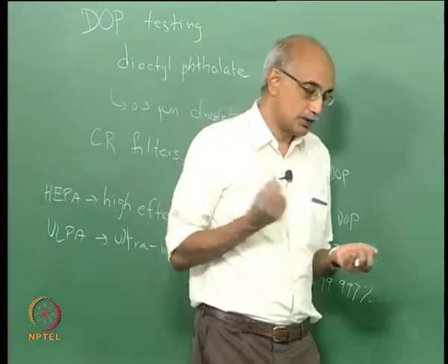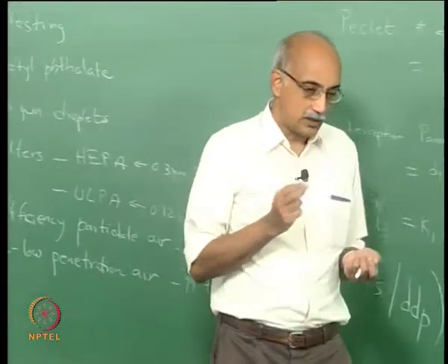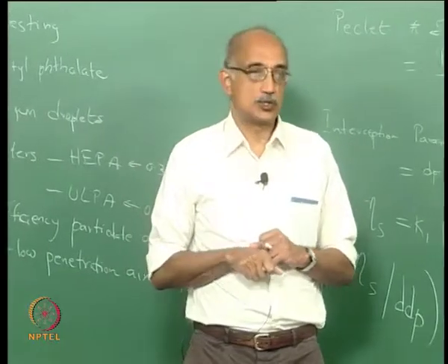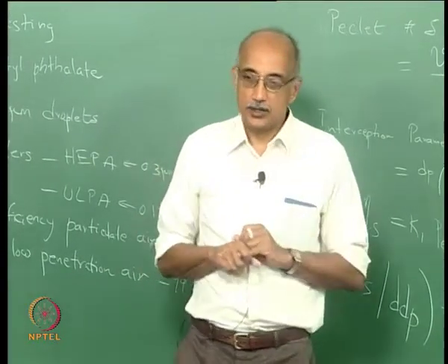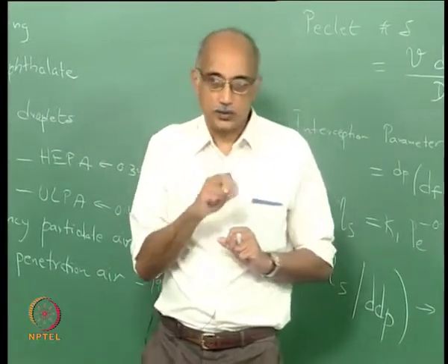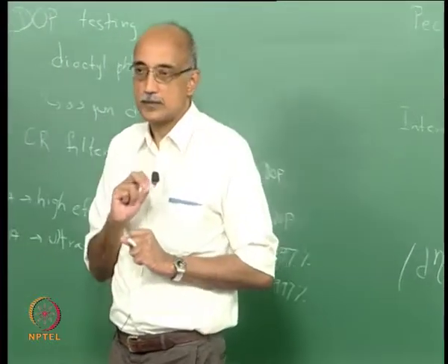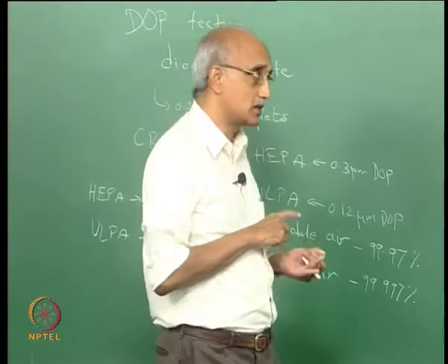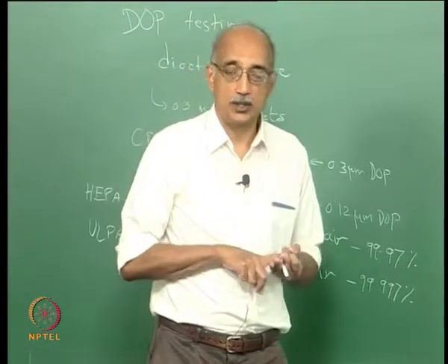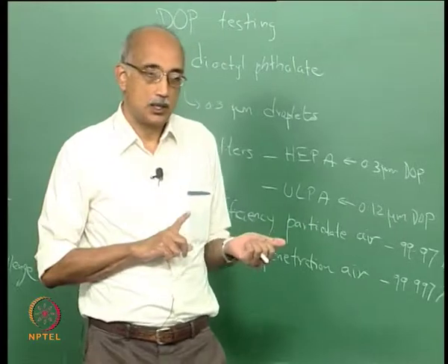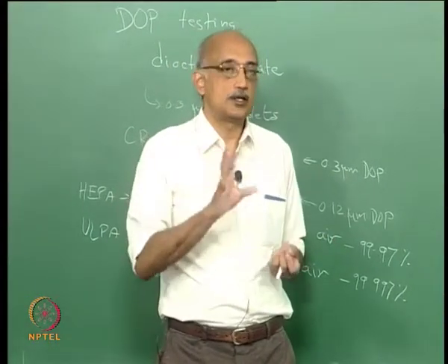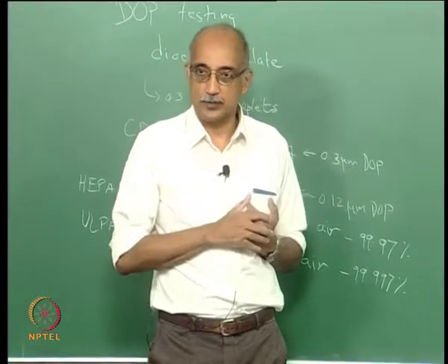So, the thing with filtration technology is the particle characteristics obviously play a huge role. Again, particle size is the most important parameter. The filtration methodology you use is very much dependent on the size range that you are trying to filter. Size and shape also play an important role, because many of these mechanisms are effective really only assuming a spherical or near spherical particle shape distribution.